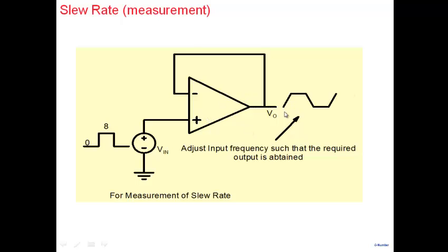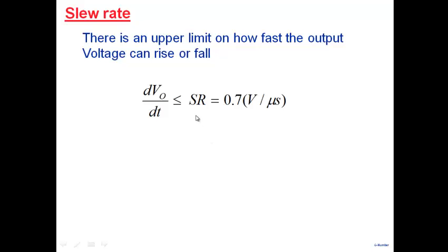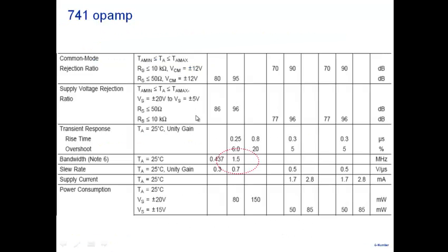So this is also an important limitation of the op-amp here. The maximum slopes are limited to the slew rate here. And I'll skip that. So slew rate is, you can see here, the manufacturer quotes roughly a value of around 1 volt per microsecond. So the maximum rate at which your output voltage can change is 1 volt in 1 microsecond. It can't go beyond that. Okay.